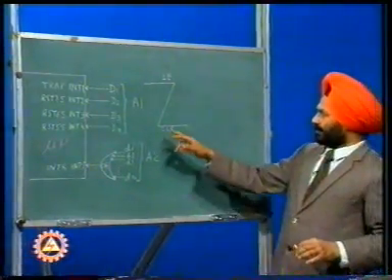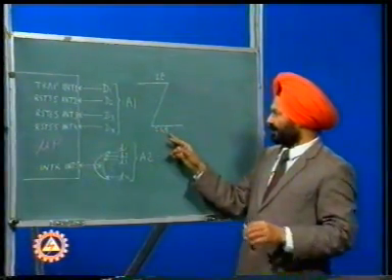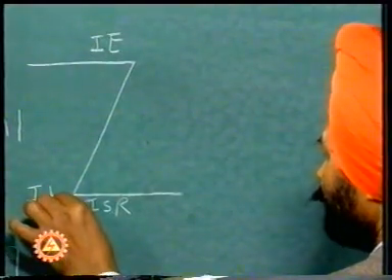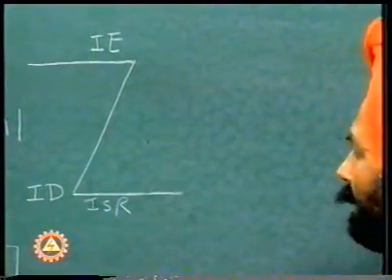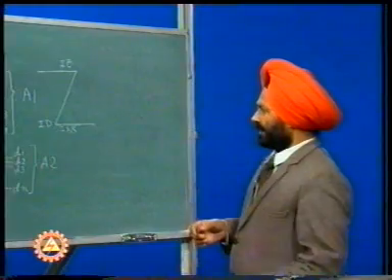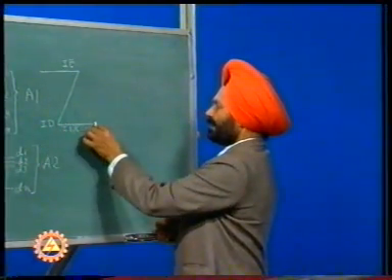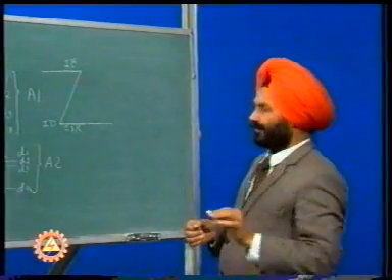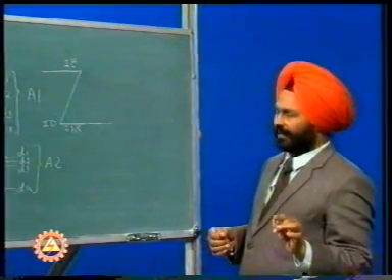As soon as the microprocessor enters the interrupt service routine, the interrupt system of the microprocessor is disabled automatically. Then during the servicing of the ISR, the microprocessor is not interrupted, of course with the exception of the non-maskable interrupt.